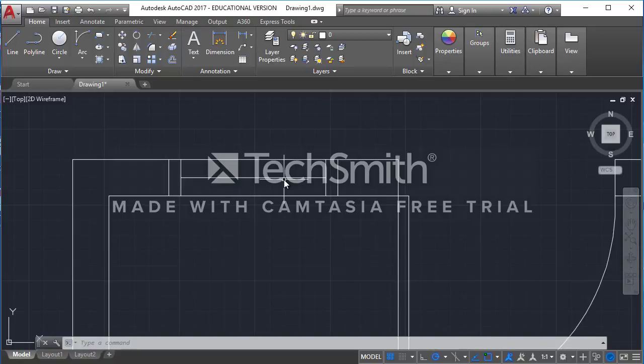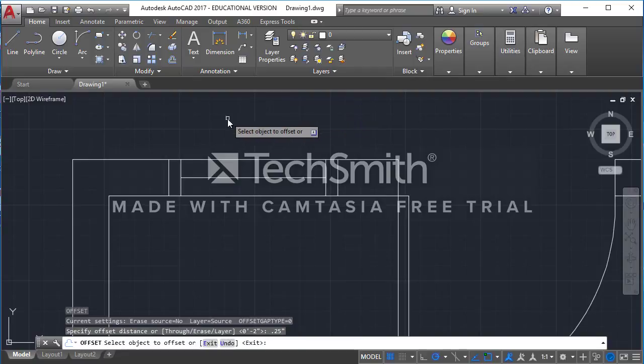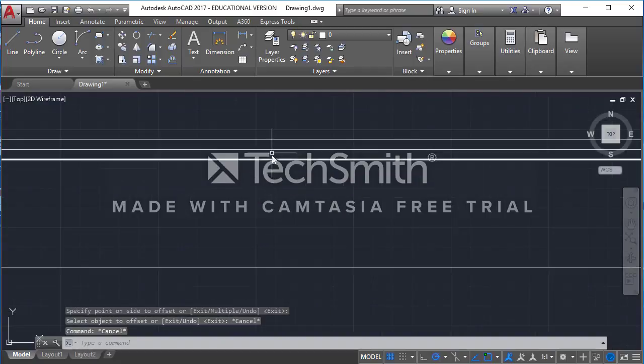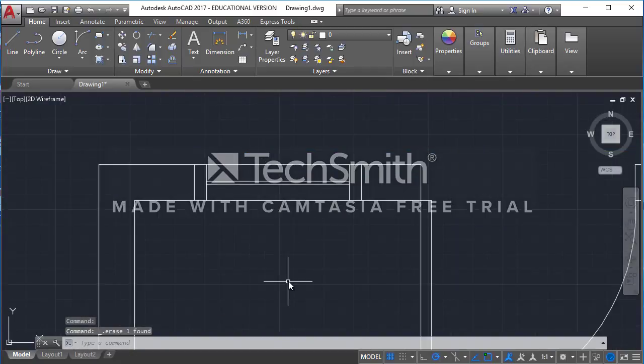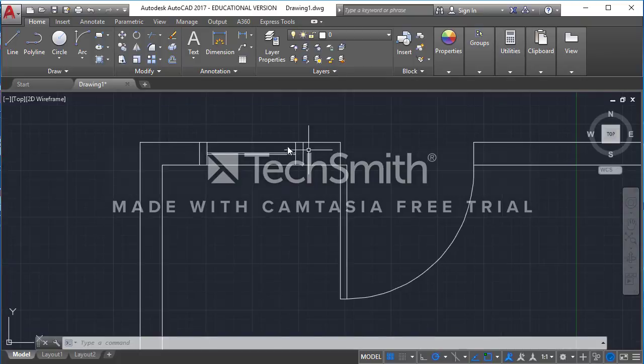So if I wanted to take this a step further, I could offset this line and give the window pane a little bit of depth too, okay? We can just say the window pane is maybe a 1/2 inch thick. So again, I could type in offset. If I know my window pane is a 1/2 inch thick, I'm going to want to offset this 0.25 inches in both directions, okay? See how I did that? And then I would delete that middle line. So that's just a basic architectural graphic for a window, all right? So there's our first window.